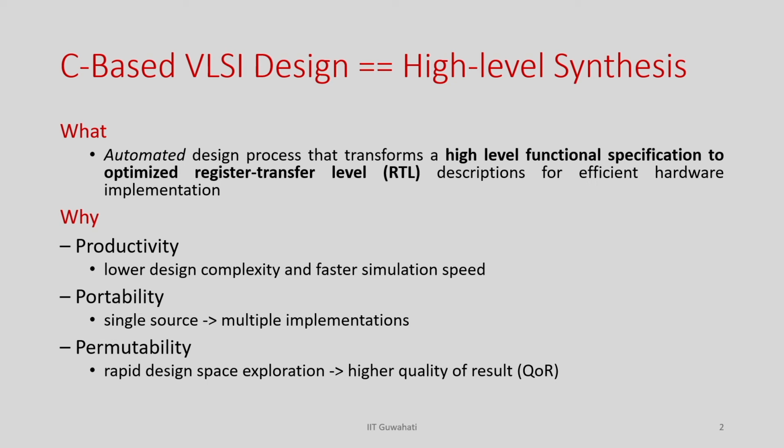But we will primarily focus on high level synthesis because that is something completely new in the context of the EDA design flow. The logic synthesis and physical synthesis parts are kind of matured. So, the primary focus of this course will be on this C to RTL conversion by high level synthesis.